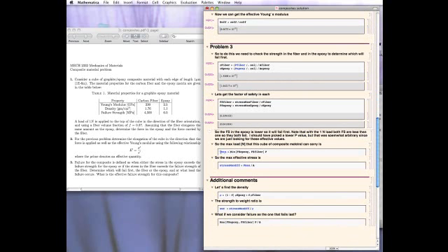So we have to figure out what is the maximum load at which we have a factor of safety of 1 or higher for both of these. Since it's a linear problem, if you halve the load, then you've doubled the factor of safety, okay? In other words, if you halve the load, the stresses drop in half, so the factor of safety doubles.